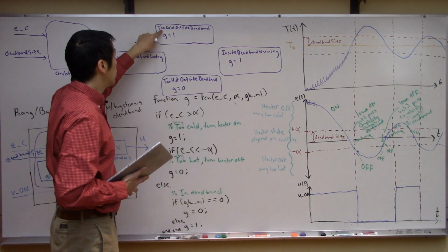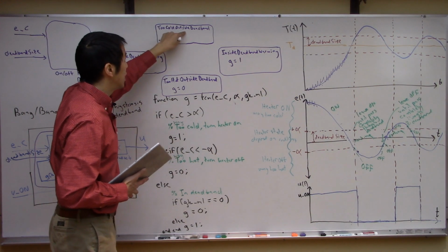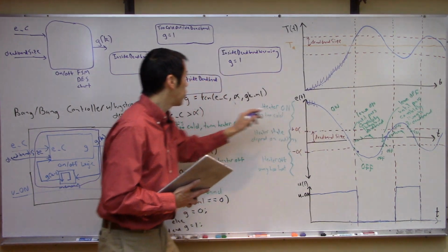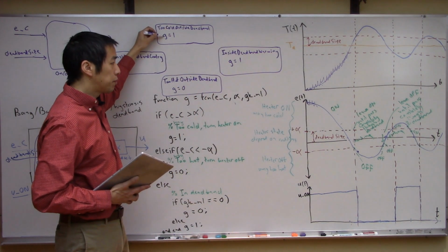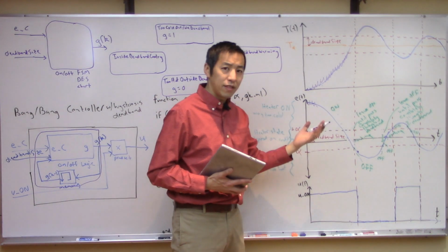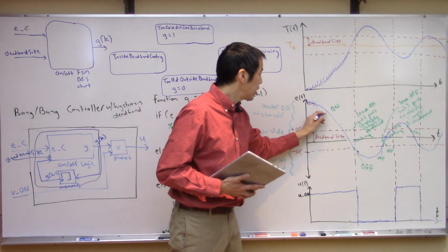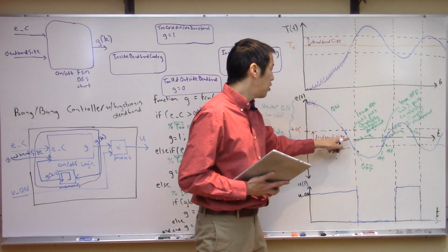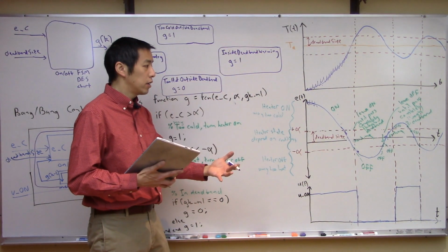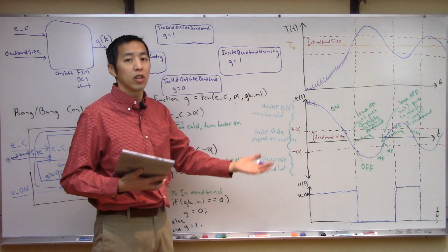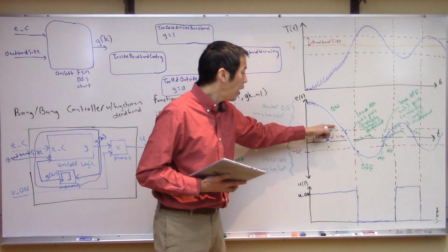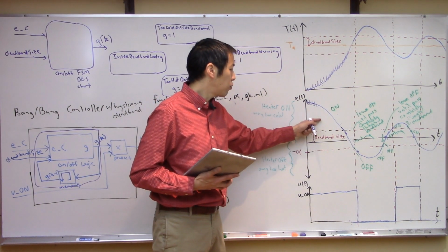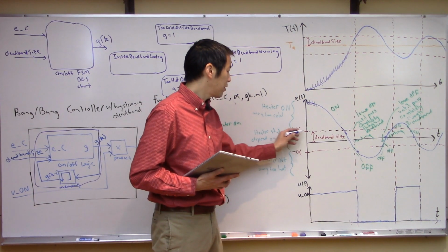So the equivalent way that we can represent this purple logic is, like I said, let's just enumerate these 4 states. You can either be way too cold outside the deadband, so that's where we started off out here. You're way too cold, so you want to turn the heater on. Now what's the next state that this system can transition to? You can go down here and enter into the deadband on the warming side, and continue and commit to warming. What triggers that transition from out here to in here? Well, that's when you cross this threshold of positive alpha.